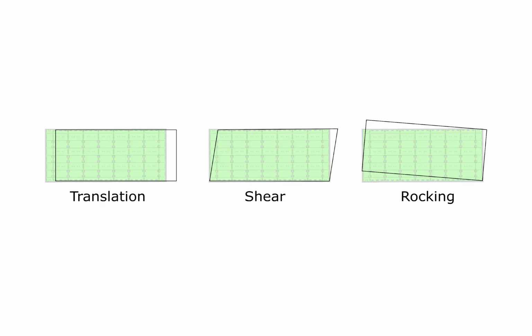There's a good paper, which I'm going to link in the description, which provides some analytical models about how to calculate cross-laminated timber walls, which are the standard solution for shear walls. I decided to adapt most of those equations to the WikiHouse wall, because I think there's a very good parallelism between the two systems. If we are thinking about pushing our wall, there will be essentially three deformations, three mechanisms that occur altogether and contribute to deforming our wall.